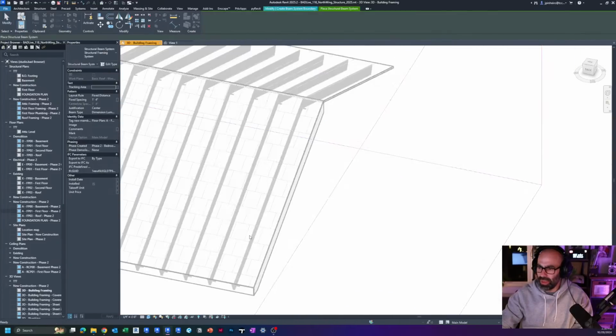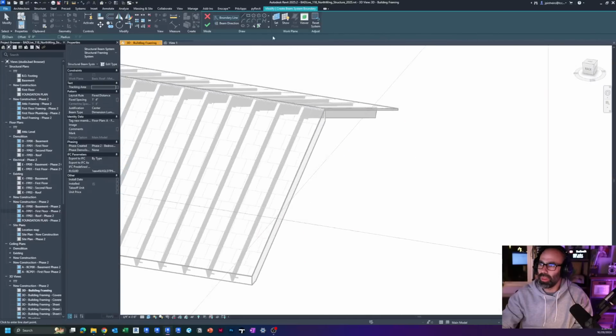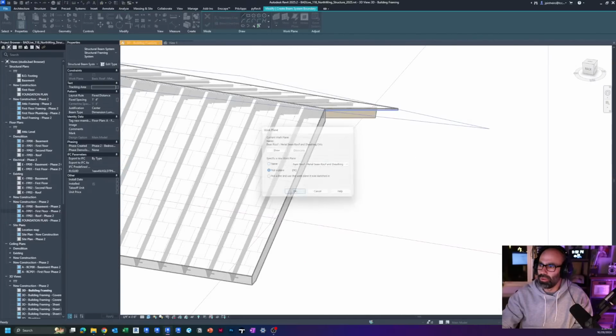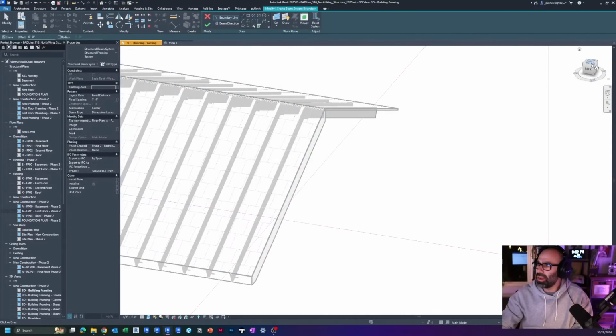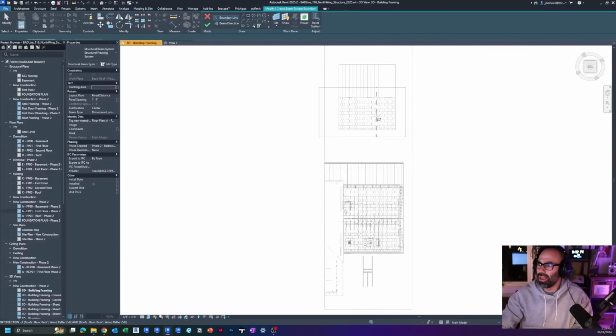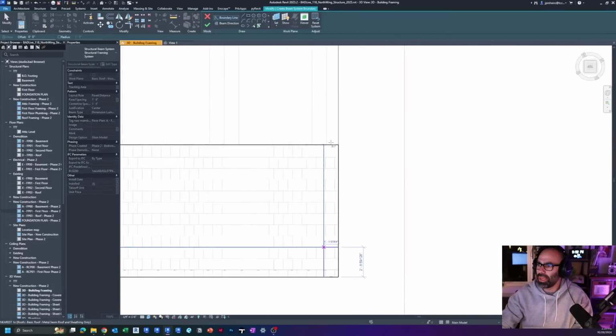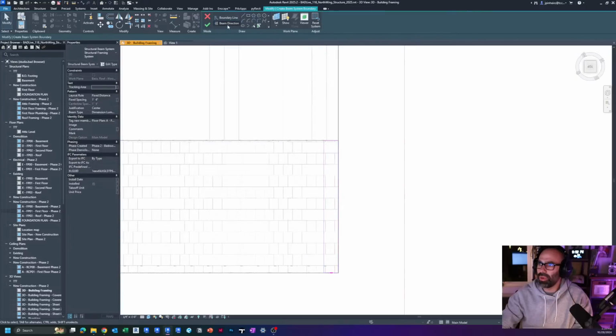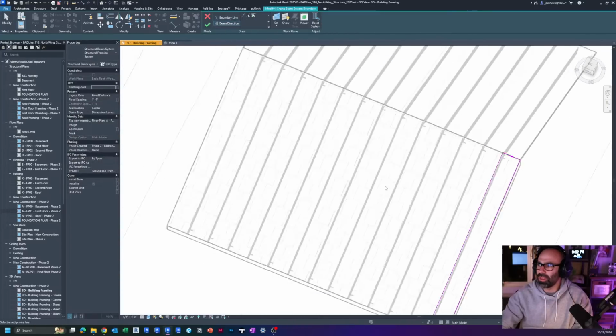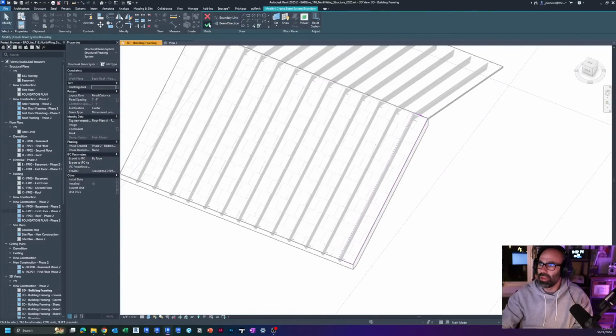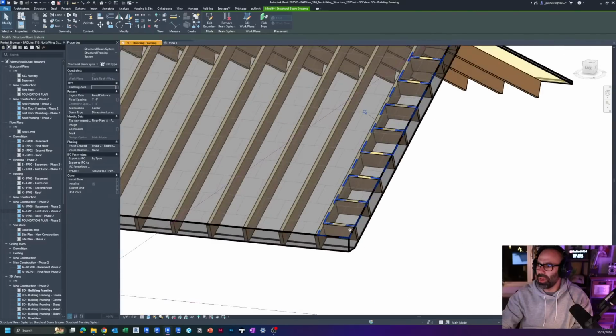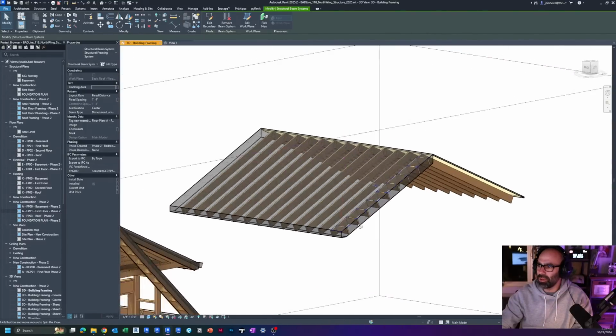I can do the same thing. I can do a beam system. I can set it to this guy, right? So now it's working on it. I can do a quick sketch to wherever this needs to be, but instead I'm going to do a beam direction in this direction, right? Click finish.